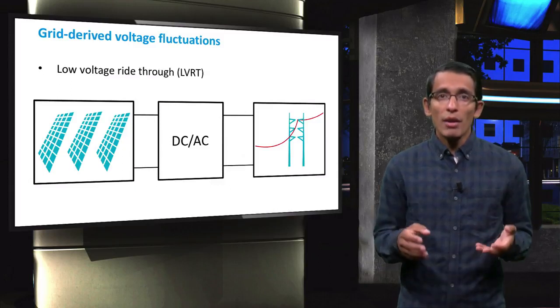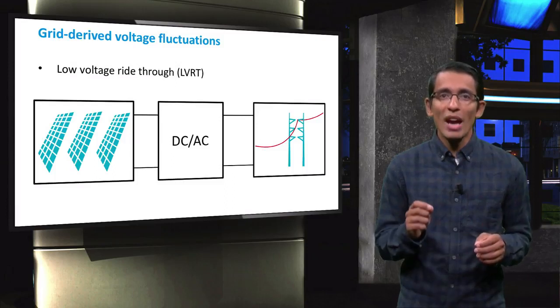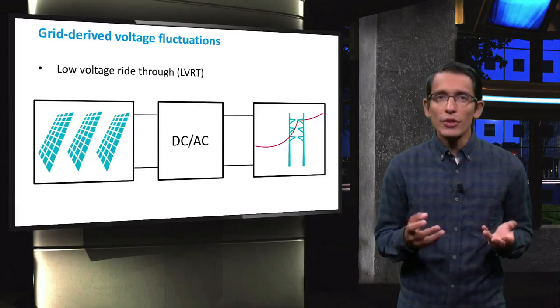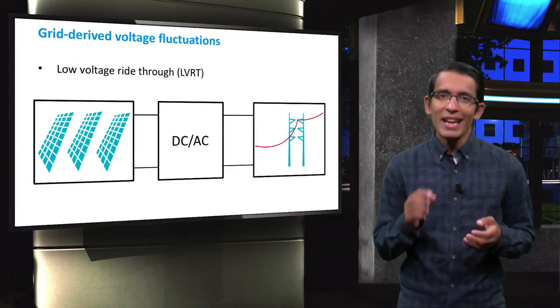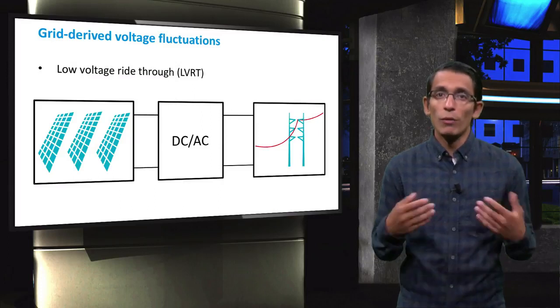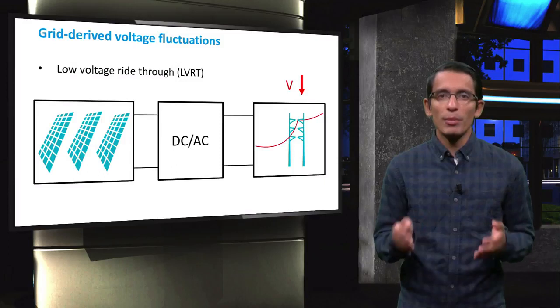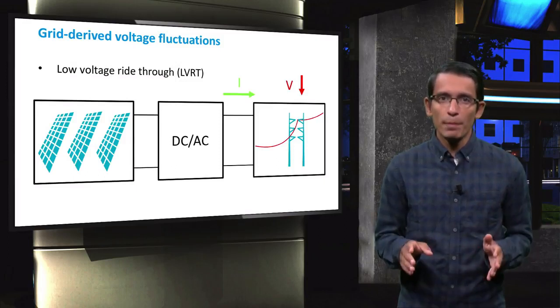One way to broaden voltage dip tolerances is to incorporate low voltage ride-through, or LVRT, techniques into the inverter design. This term refers to the capability of electric generators to stay connected in short periods of lower electric network voltage, or voltage dip. When the voltage of the distribution system goes down, the inverter is programmed to keep injecting current into the system.